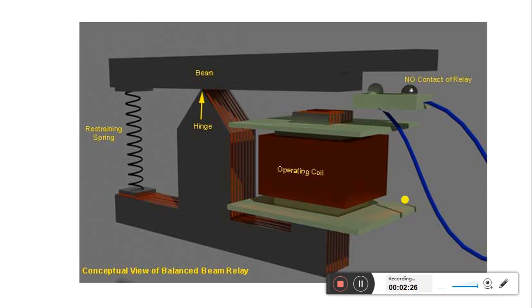As in previous classes we have discussed how the distance protection operates: once the impedance measured by the relay is less than the set value, the relay operates, and if the impedance measured by the relay is more than the set value, the relay will not operate. It means the fault is outside the zone.